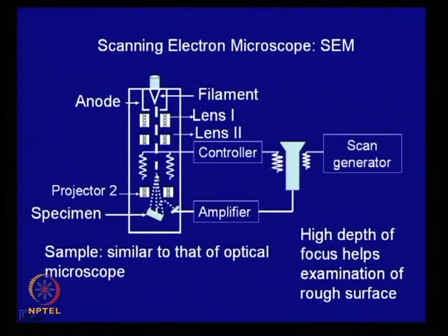And what you collect from here is, when this beam strikes, some of the electrons are reflected and some penetrate a little and some secondary electrons are emitted, and you get maximum information if you can collect these secondary electrons in this collector over here, a scintillation counter.